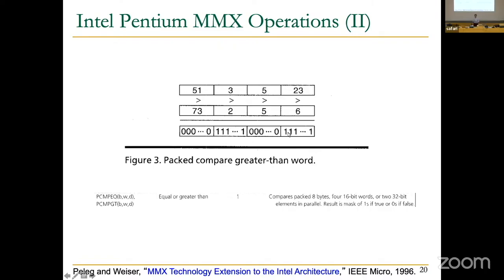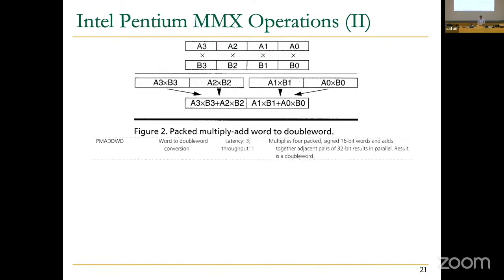So now what you're seeing here is you're creating a mask. Remember the vector mask register? We had that as a special register in a SIMD processor. Well, we have it in a general purpose register over here. The destination register specifies the mask. And we're going to use that as a data element to actually decide which operations take effect or not by programming this in a nice way. Does that sound good? Okay, so you can see there are many, many operations.